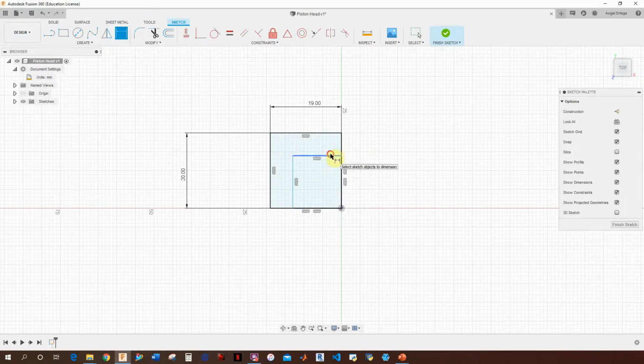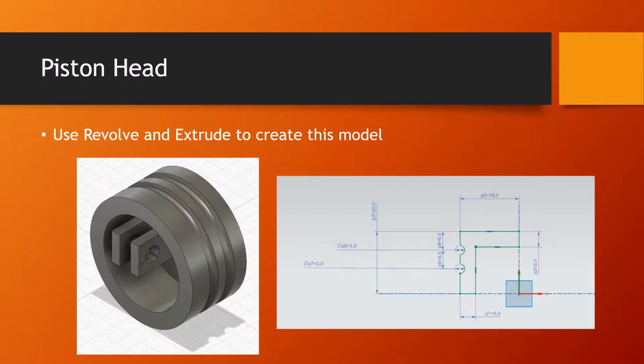Now this one has to have a difference of 5, right? So 5 there and 5 there. There we go. And now if I jump back into the sketch, we can see that we have pretty much all of that done, and then we just need this circle. So the circles are 3 millimeters in diameter, and they're positioned at 6 and 6 vertically, so 3 and 6.